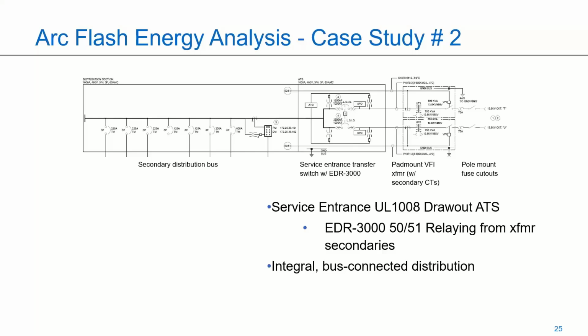All right, so looking at the setup here, in this case, we have a pole-mounted fuse cutout in the green box. Those are utility-owned and not very tightly coordinated. Although in some cases, the utility may be able to work with you to tighten some of those protection settings. It's very often likely feeding multiple customers as well.